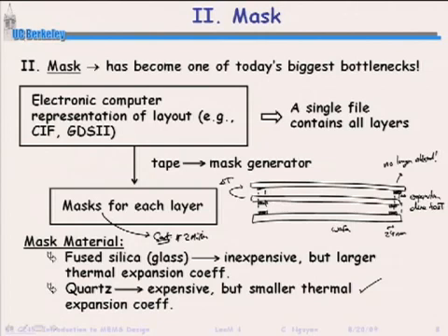Okay, how do you solve that problem? That's one of the biggest dilemmas I know that the government is trying to solve right now. Because we need those custom integrated circuits, but they're starting to cost too much if we're using the latest and greatest technology. So one of the solutions to that is a lithography system that doesn't use masks. Okay, you may have heard about direct write lithography systems. E-beam systems are like this. But the problem with those is throughput is not high enough. But there are people doing research to try to create direct write lithography systems that can directly write your chip using laser light sources or so, and many of them in parallel, without the need for a mask.